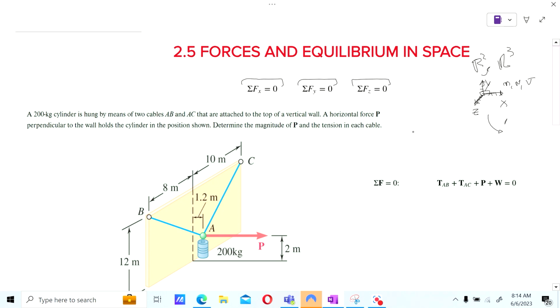What that means is that if you have a force going to the right and another force going to the left, for this to be static, these forces have to add up. And the easiest case is if they're completely horizontal, F1 equals F2. But in this case, it's not so straightforward because the angles are different. So what we do is that the components in x equal 0 and the components in y equal 0. All right, so that's the concept. Let's look at an example here.